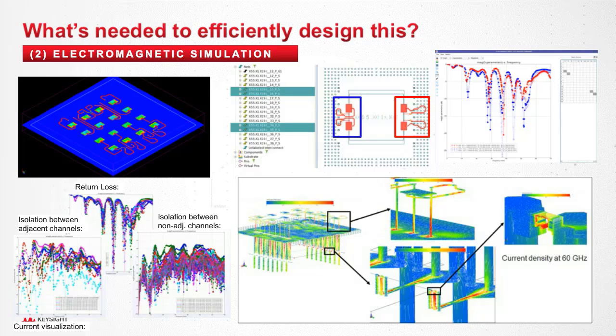And then that's what we're actually going to take to the second challenge in the design process, which is electromagnetic simulation. We've got to take that thing and then efficiently get electromagnetic results out of it, which is a really big challenge, because if you consider the geometries involved, you're going from very, very small geometries on the chip to quite larger, and could even get larger on the board geometries of the phased array. And then underneath, if you've got the board, that's going to be even bigger geometries. So there's all the traditional things. Of course, we can try to characterize the package. So you need to be able to look at all the packaging stuff as it is. But also, one of the challenges, if you're thinking about the circuit design itself, if you're going to co-design the circuit in the package, what I'm showing here on the top is we always think about simulating the entire phased array all at once, the whole thing.